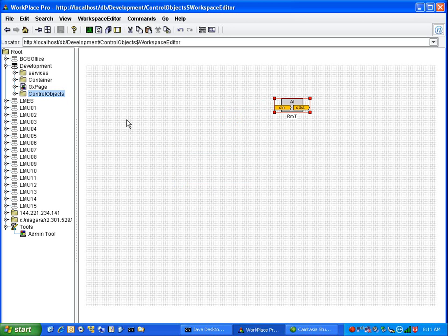That will link right to a BACnet object or a LON controller or something that's not going to be labeled quite like that. A lot of times in the programming world, we try to make things a little easier for the people who have to follow the software, and we make these little AI tags for everybody so you don't have to open up a Workplace Tech program to figure out what this point is. So we clearly know that it's a room temp.